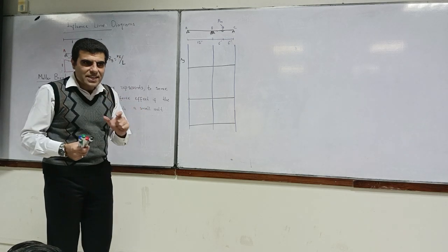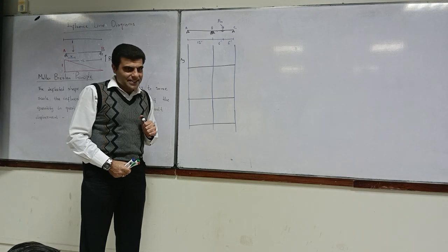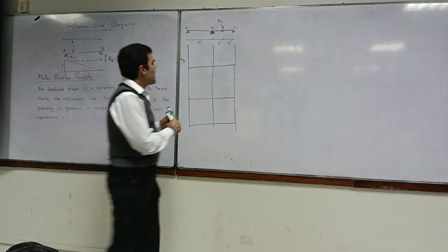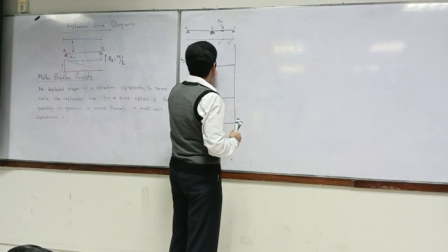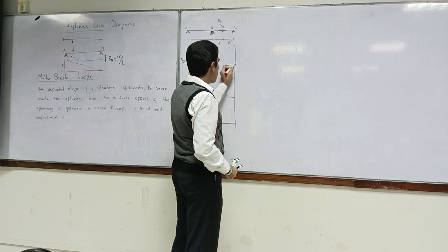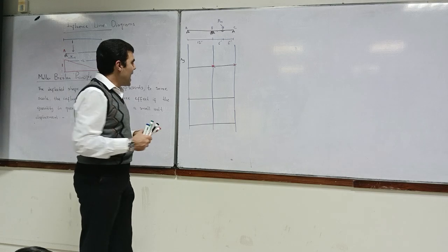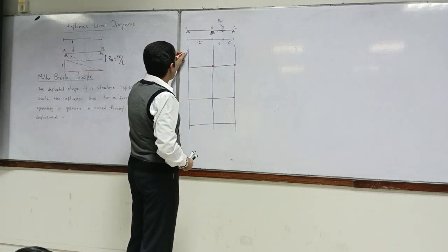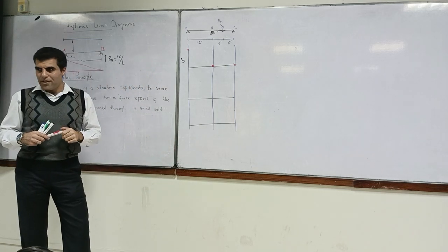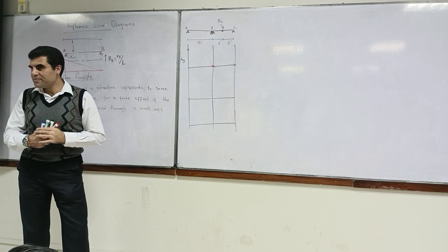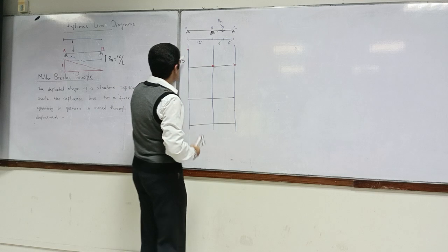Okay, first of all, let us see which points won't deflect. B and C. So B shouldn't deflect and C shouldn't deflect. Zero, a constant line. Is this a constant line? And this one should be a triangle. So what do you think? What should we do? Linear, yes. Linear, you're right. So let us draw a linear.